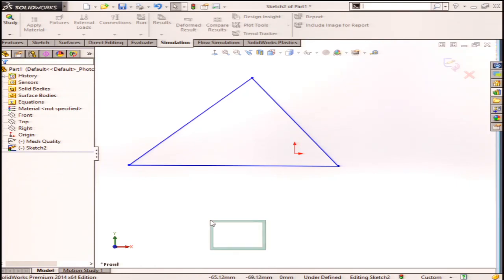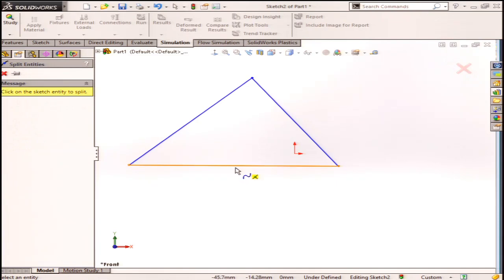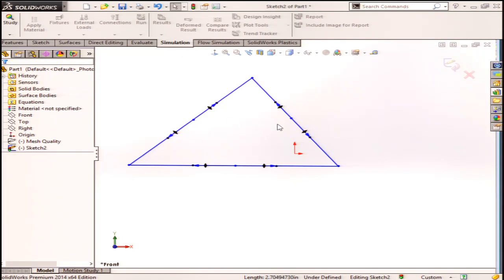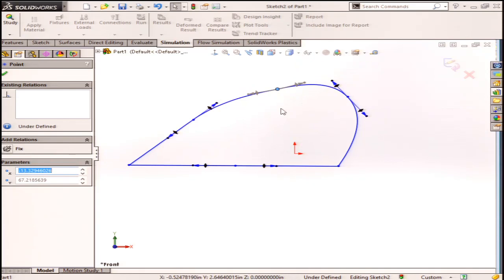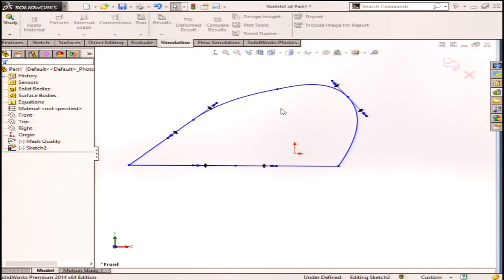If I add those, the difference between high quality and draft quality is just what we call a mid-side node, a node that gets added right to the center of each of the edges. So by doing this, I can actually come in here and pull on it and displace it. Now, that displacement is not a straight line, but it can map to the exact geometry via a parabola, which is a much more accurate capture of how this thing's really deforming. So does that make sense to us? I mean, that is called Jacobian. We don't want to deal with that. So does that make sense to you? All right, so